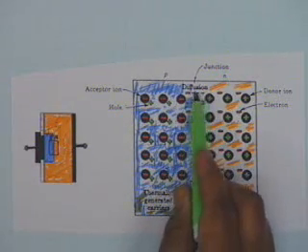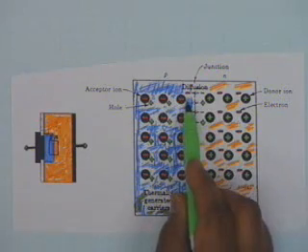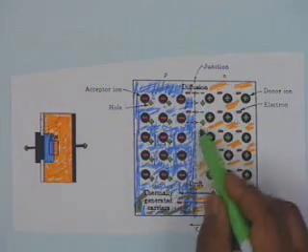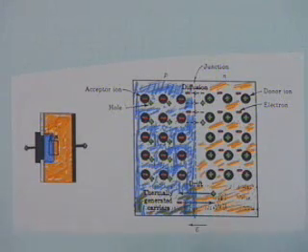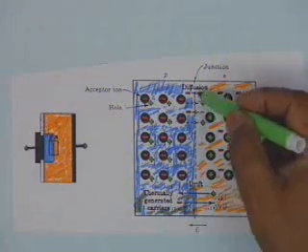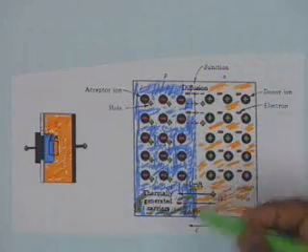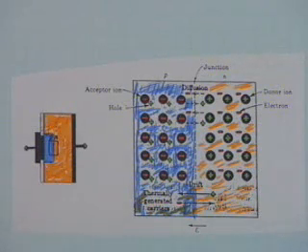There is an electron which has come from this side, there is a hole which has gone from this side, and I have shown this part as empty. Why empty? They have already recombined, and therefore if the device is left to itself, then a region near the metallurgical junction shall be devoid of charge carriers. Isn't that right?